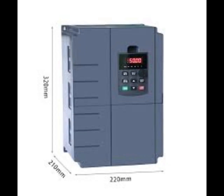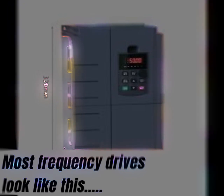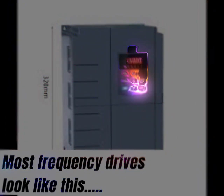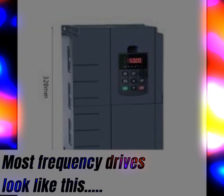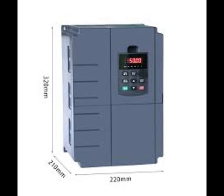This feature can be a real advantage for some types of loads, especially gear-driven loads. The amount of acceleration and deceleration time can generally be adjusted by setting potentiometers on the main control board. Some other adjustments can usually be set by changing potentiometers as follows.